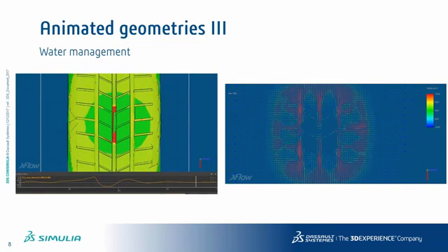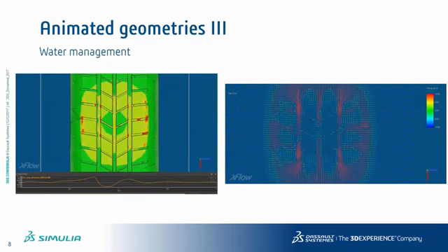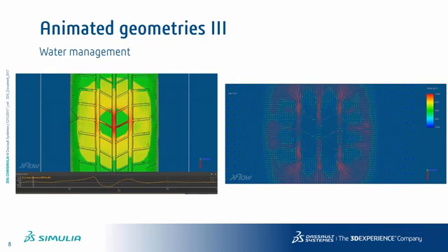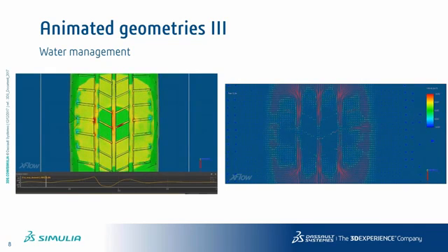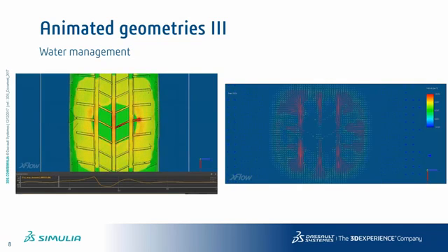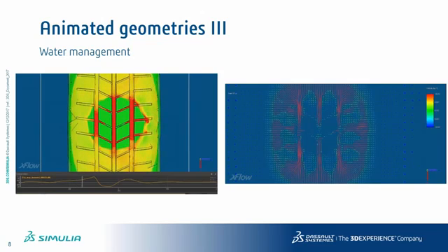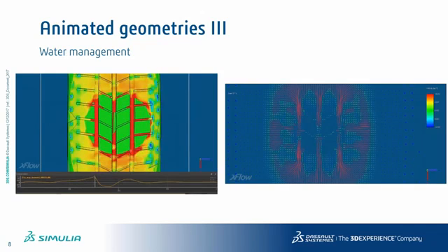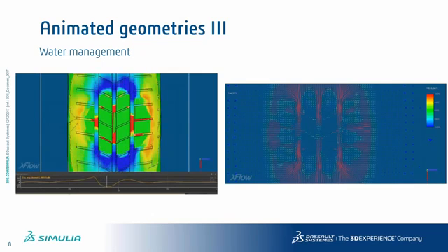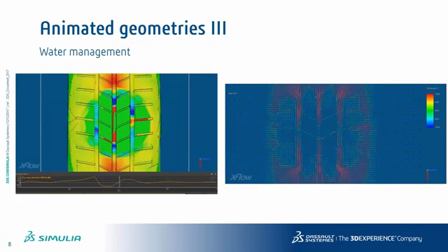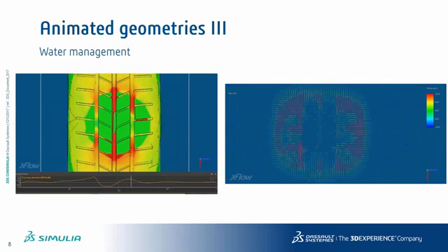And we have a plot of the forces which the water actually applies on the tire on the bottom part of the video. And as you can see, as we squeeze the tire, of course we have fluid that goes through the threads, and there are high velocity regions, so the fluid is actually evacuated from the threads. And you can see the green patch, which develops, which is basically the place where water is gone because it's been expelled from the tire threads, and then the tire is pulled back. So then we have a release of these velocity vectors.